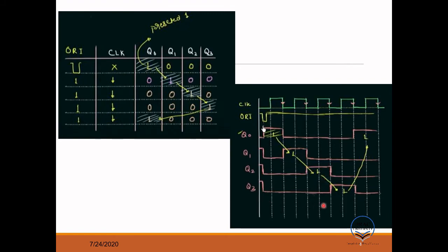So for this one again, it will change state at the clock edge here. So 0 becomes 1. And at the next clock edge it will change state, and for input 0, output will be 0. Okay. So if you look at here, 1 1 1 1 1. So it's creating a clock. So that's why this ring counter is forming a ring kind of structure.